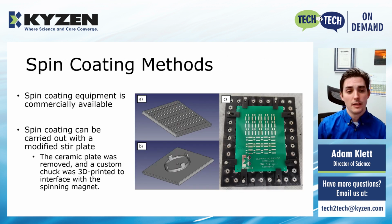All right, so how are we going to do the spin coating? Well, spin coating equipment is commercially available. You can go online, and there are various items out there ranging anywhere from a few $100s to a few $1,000s. If you don't have spin coating equipment, or you don't have access to spin coating equipment, you can carry it out with a modified stir plate, which is what I'll be showing here in this example. Here in this work, we used a modified stir plate where we removed the ceramic plate off the top, and then we custom 3D printed a chuck to interface with the spinning magnet, as you can see in the diagram to the right. And then you can see the sample board clamped into the chuck there.